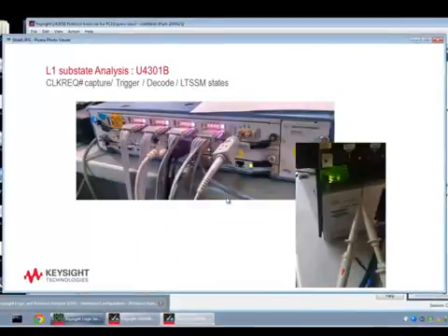My analyzer is able to capture the data using a standard scope probe using the sideband signal acquisition. While data is flowing across my acquisition points, this probe is connected to some point on my target, whether it's an embedded signal or any one of the interfaces. I can bring that signal back into my analyzer, and this will work with the U4301A or B analyzer. Just need the new analysis software. So I connect up to capture that data.